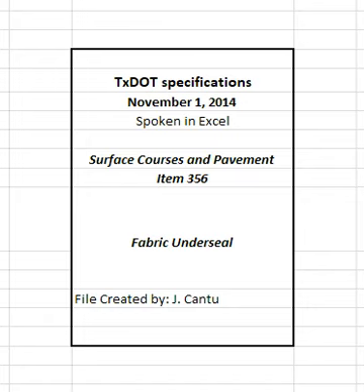4.2.2.1 Non-woven fabric and binder. Apply asphalt binder as directed in section 356.4.1.2, asphalt binder application. Place fabric as directed in section 356.4.1.3, fabric placement, except do not allow joints or laps in the underseal material along transverse pavement joints. 4.2.2.2 Reinforced joint fabric. Remove any protective coatings from the adhering layer of the fabric underseal. Roll fabric in place to ensure adherence of the self-adhering binder.